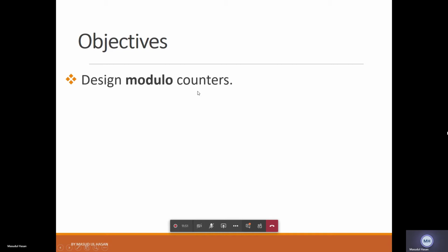So this is frequency division from 100 megahertz to 1 hertz. So how to get this? To generate a signal with a frequency of exactly 1 hertz from 100 megahertz, we need to count the exact number of 100 megahertz cycles that make up a single 1 hertz cycle.